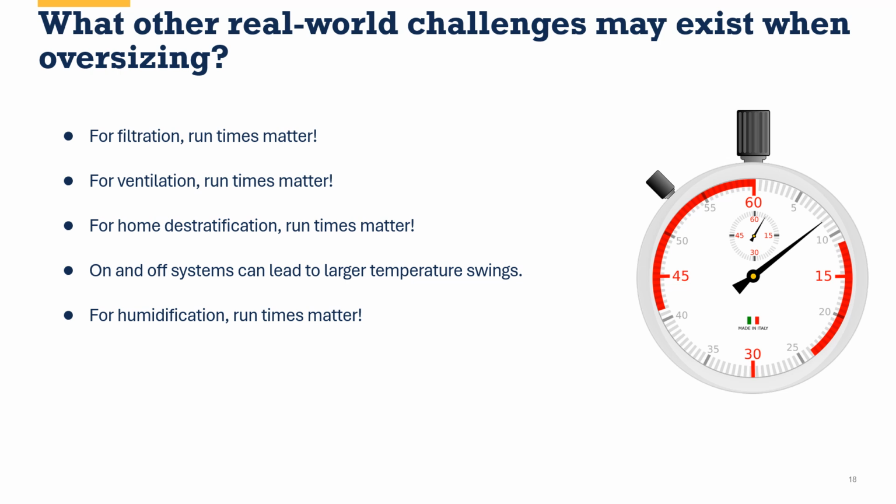Now, if you're watching this and you're not in Colorado, you're in a more upper Midwest state, it could be the flip side. It could be dehumidification. Same challenge. If you are trying to use dehumidification, either the air conditioner function or an external dehumidifier, same thing happens. We need to have these run times to make it work. I'm not going to get into it in these sessions, but when we do specific training in the Midwest, there's a lot more that we focus on for dehumidification because there are some additional challenges beyond just runtime.